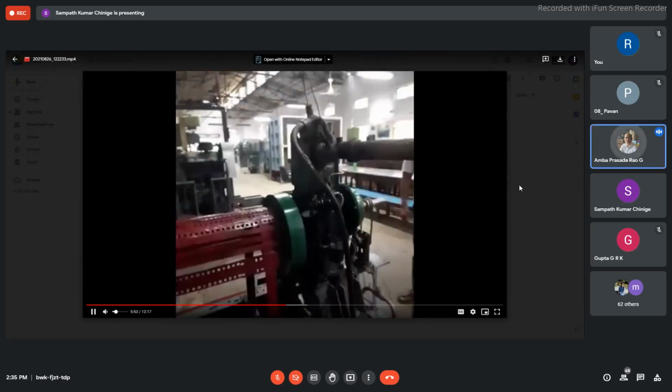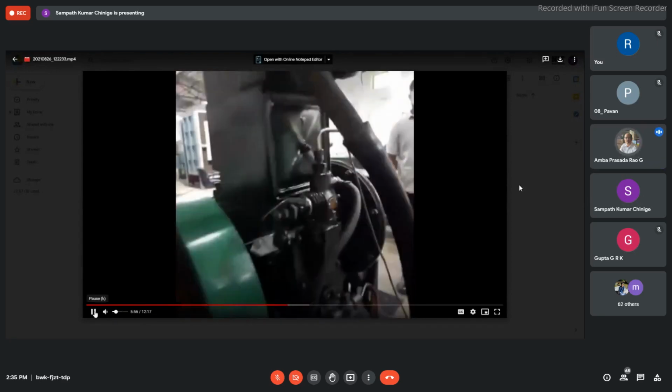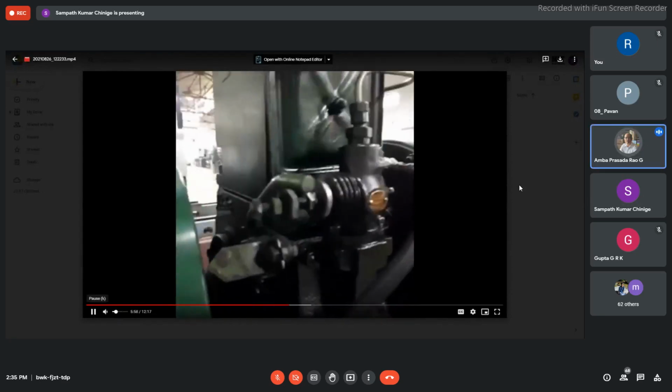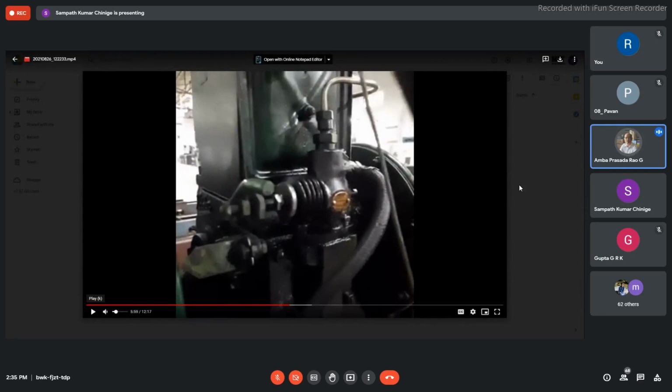See the inner dial reading also. It has changed to 1500 rpm, and there is a lever here now with the help of bellows. Now you can adjust so that more and less fuel can be regulated. That is entering from the fuel tank through the plastic tubing through this fuel filter. From the fuel filter it enters into the fuel pump to the injector, which is located on the top of the cylinder head. Whereas this rack pinion arrangement is there, so this will regulate the amount of fuel.